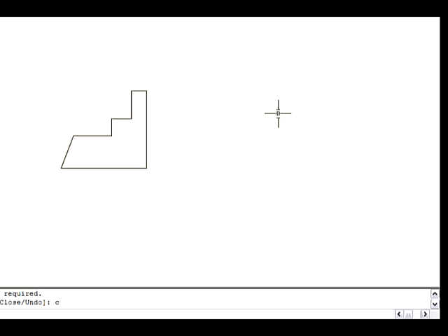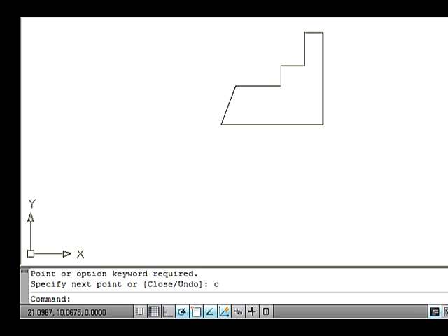As in most other Windows programs, Escape is the cancel key. Unlike many other Windows programs, AutoCAD keeps you well informed of whether an operation is in progress. The blank command line indicates that AutoCAD is resting, waiting for your next command. Press Enter to accept the default action.